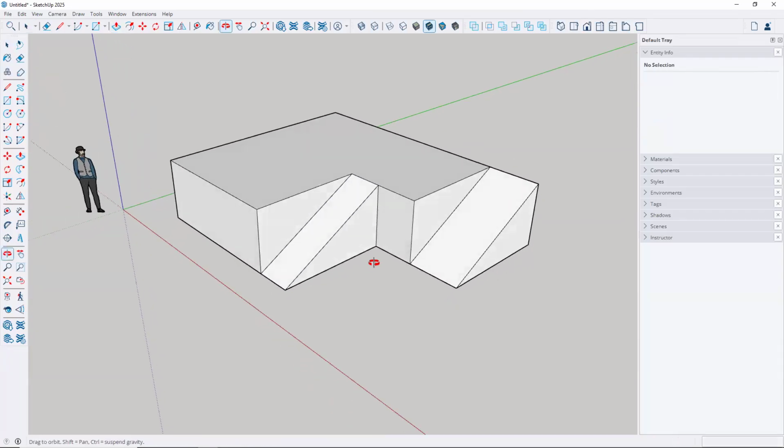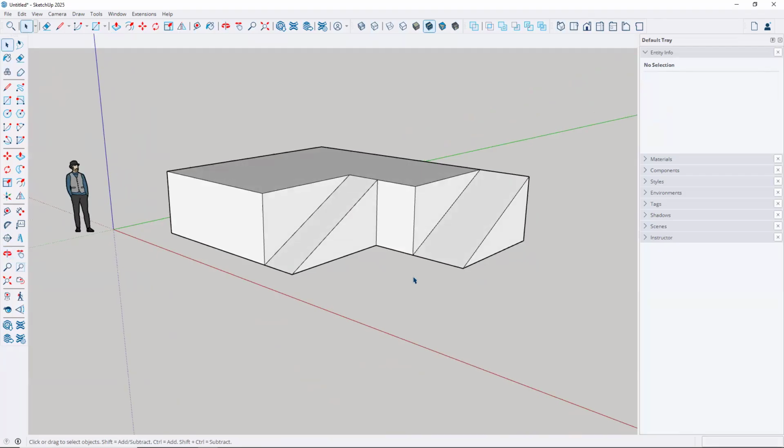And then the last thing I want to do here is point out another big key concept to SketchUp that is really, really important to understanding if you're going to use SketchUp successfully, and that is making groups. So anytime you make these shapes, these 3D solids, it is so important that you make a group out of them. You'll see why in just a moment. In order to make a group, you have to triple click on any one of the surfaces or any one of the edges. And triple click, it's tricky at first.